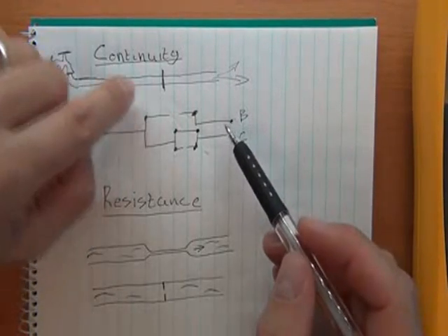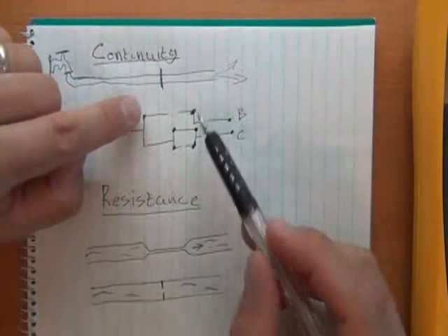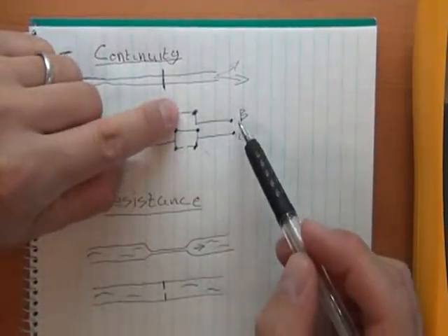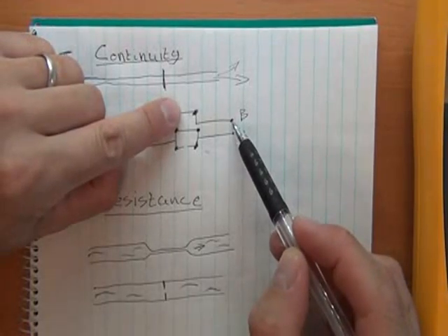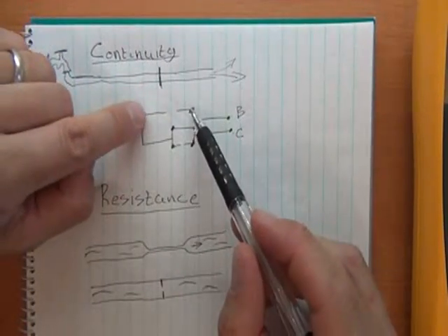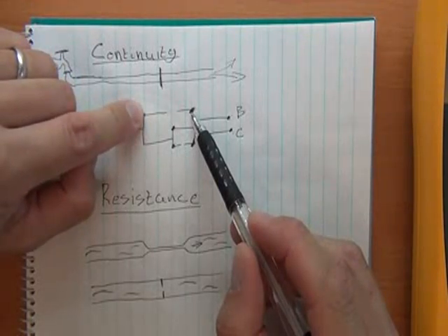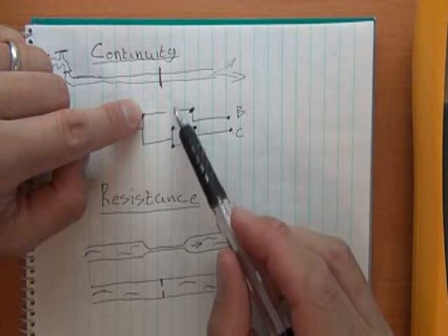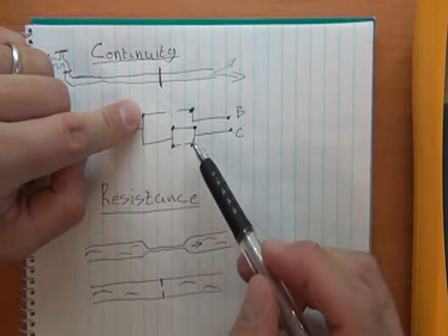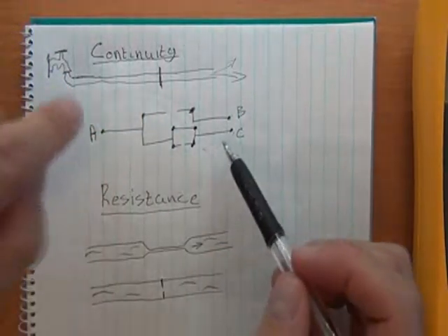So then we'd have to start troubleshooting, and we'd take our multimeter and we could take it between another 2 points in the circuit over here and check, and yes, we'd have continuity over there, and we could take it between these 2 points over here and we'd realize no, we didn't, and that we could then start isolating and troubleshooting where our break in our circuit is. Now this can get quite complicated.